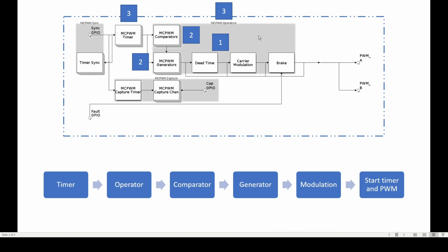My approach is by using dead time. It means that I need to add delay on the rising edge, or the positive, and add delay on the falling edge, so the waveform can shift from zero phase to 180 degrees. I will explain it a bit here.